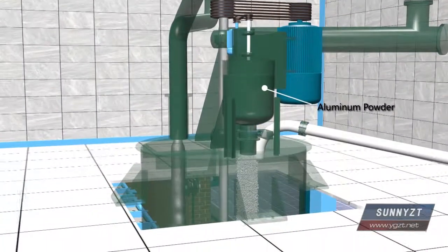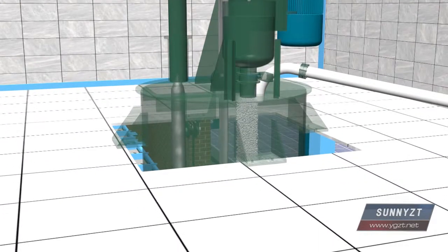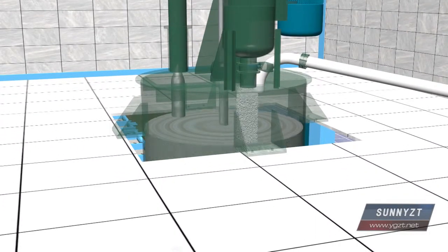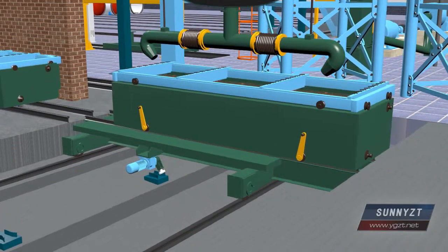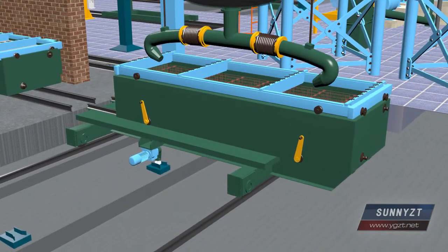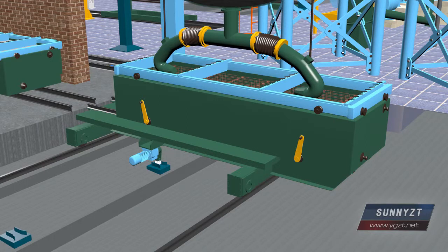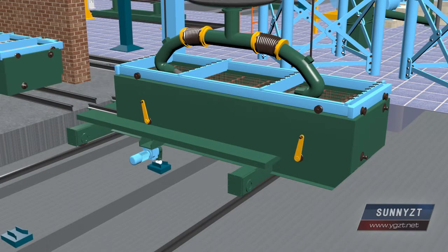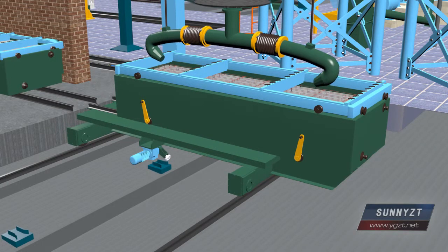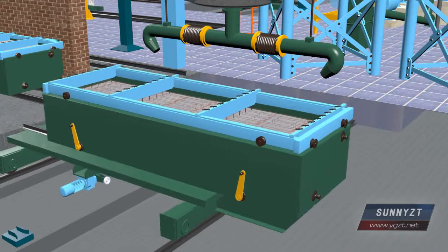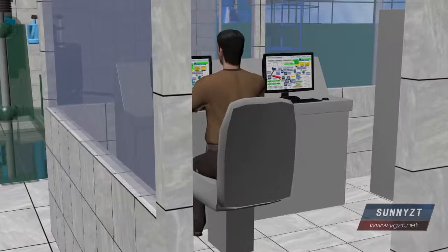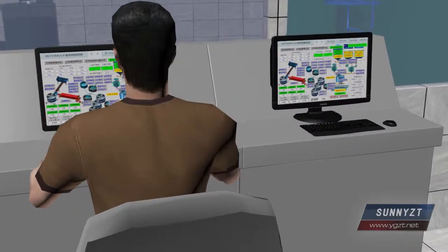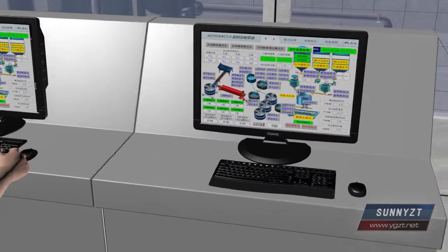Put the materials above into the pouring blender in order to do high-speed stirring for 2 to 3 minutes, and then pour them into the molding box that has been assembled. Adopt PLC automatic computer control in terms of the batching and pouring system. Form precise process formula based on the testing result of chemical constituents of the raw materials.